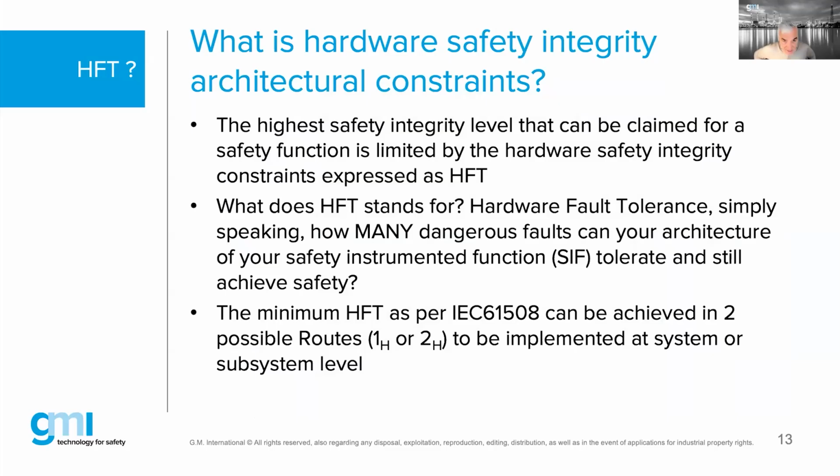Even when GMI is developing, and I'm taking as an example their SIL 3 interposing relay, when GMI is building a SIL 3 interposing relay, I can tell you now already, it will not be achievable with a single contact able to remove the load from, for instance, your field device or your solenoid. That means the internal architecture is typically more than one contact that needs to be able to remove the power to the load.